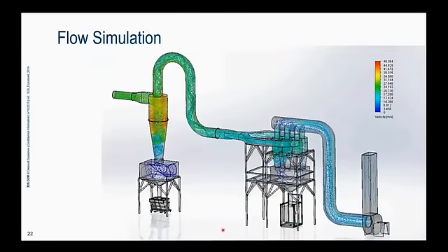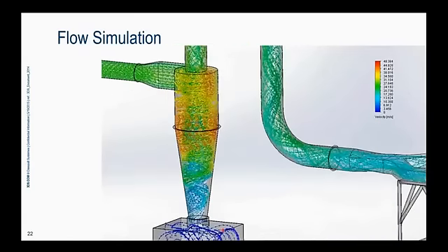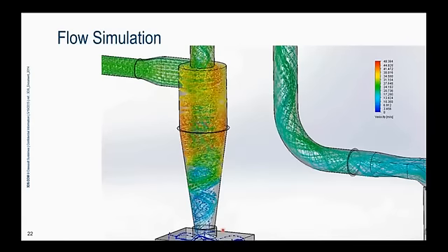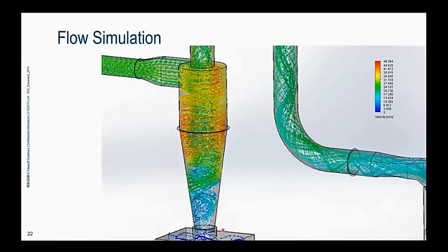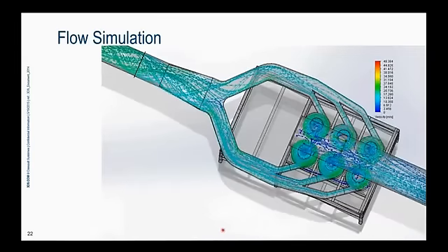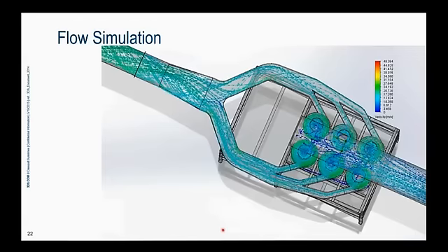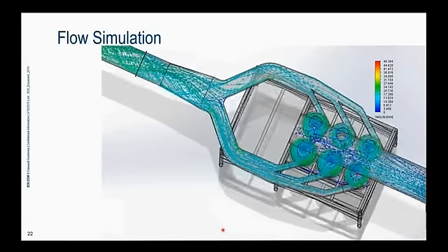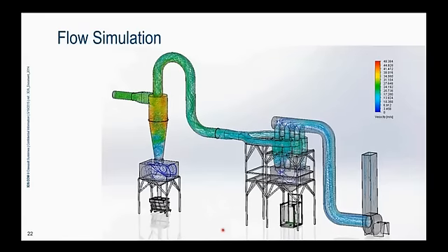So for this dust collection system, we have these cyclone separators. The main one is for getting rid of the large particles. They just get spun in this vortex to the outside wall to fall down into the dust collection. And then the smaller chambers get the lighter particles to fall down into that chamber as well. And then any remaining air just goes out through the fan to be exhausted.